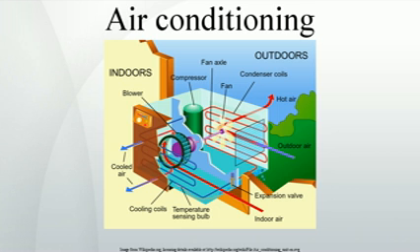PTAC systems may be adapted to provide heating in cold weather either directly by using an electric strip, gas or other heater, or by reversing the refrigerant flow to heat the interior and draw heat from the exterior air, converting the air conditioner into a heat pump. While room air conditioning provides maximum flexibility, when used to cool many rooms at a time it is generally more expensive than central air conditioning.